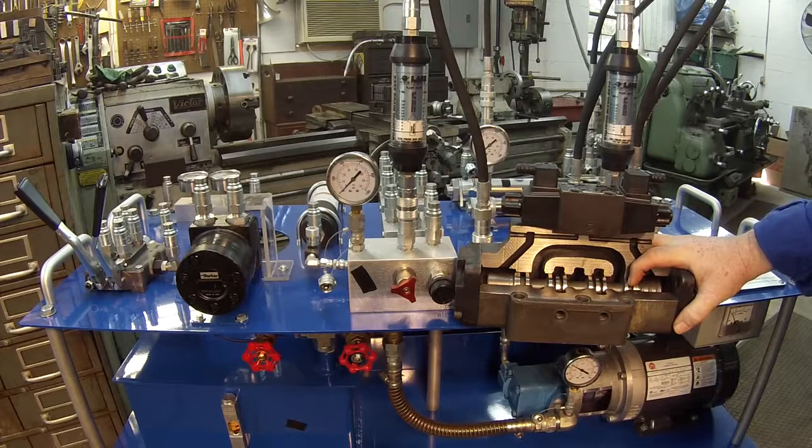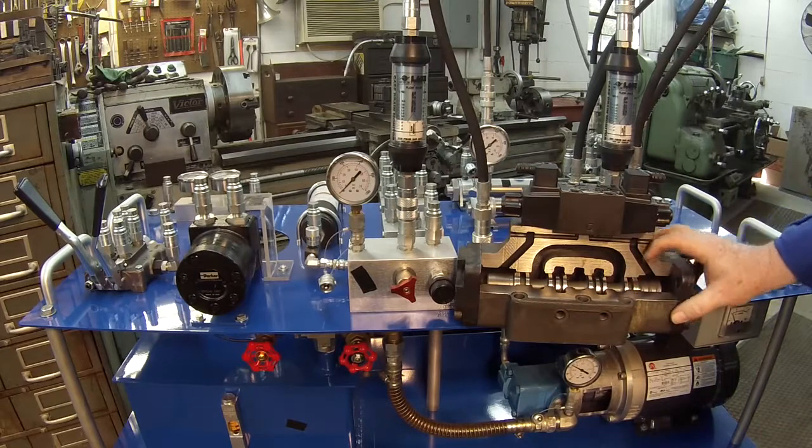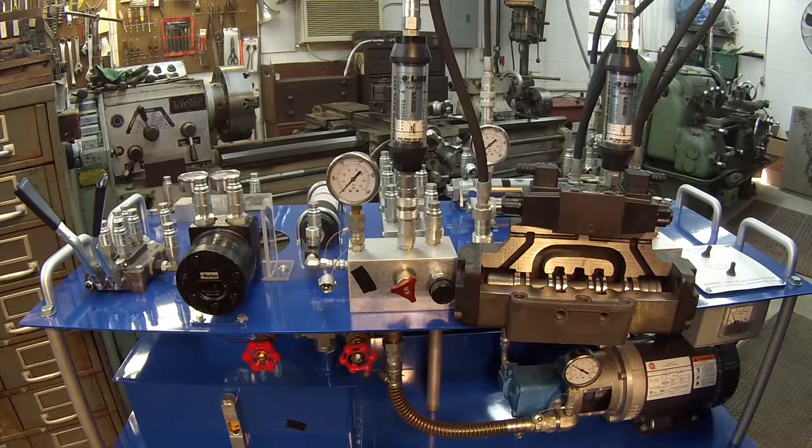Okay? One of the things that I often hear when I go in and out of facilities is, it's mechanical, no, it's electrical, it's mechanical, no, it's electrical. All right, on these directional valves right here, this is called a manual override. So at 2 o'clock in the morning, if your actuator isn't moving, you can get a push pin or a little Allen wrench and push that right in, and it'll manually shift this valve. If your actuator moves or your motor starts turning, then that tells you that you've got an electrical problem. Okay? That's one of the biggest things I run into out there at 2 o'clock in the morning.